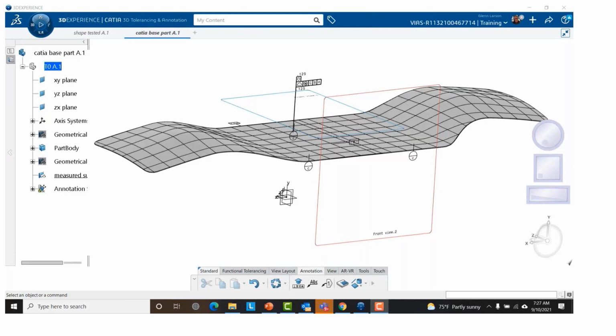If you import a point cloud and there is an area missing, can it be patched? Yes. Actually, there's some automation on that. On the 3D Experience platform, and even on CATIA V5, when you apply a mesh, you can tell it to close holes.